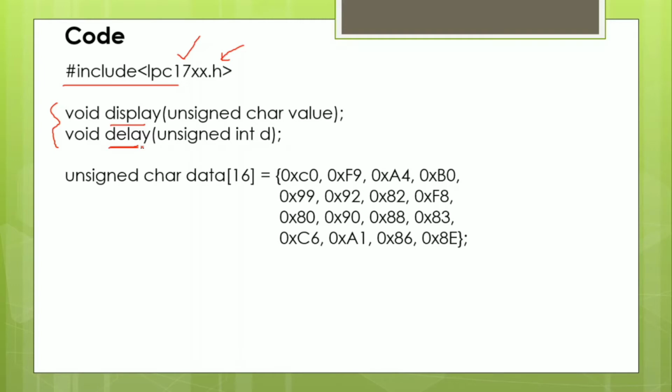The operating frequency of your LPC1768 is very high, and our eyes are not so sensitive to read at such a speed. Therefore we usually induce this delay to make us able to analyze. So this delay is to generate delay between each display.